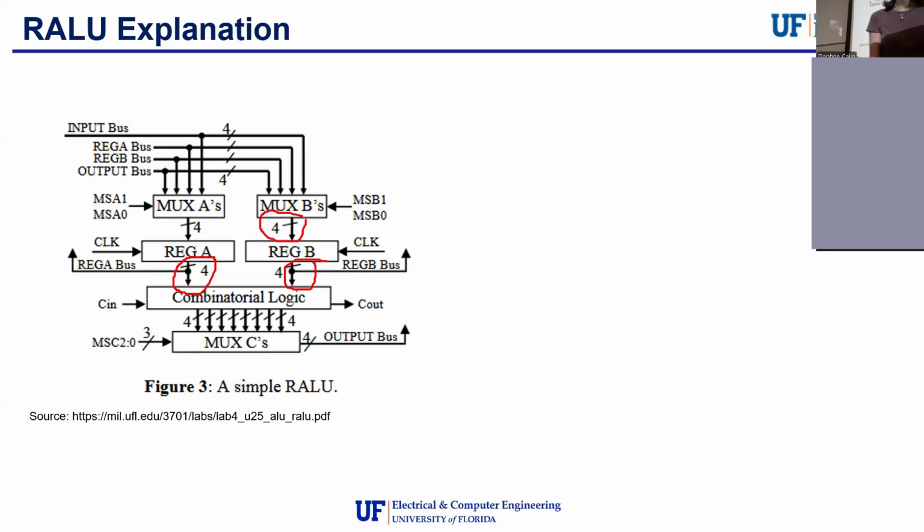Okay. For the presets and pre-clears on the flip-flops, do we have to worry about resetting them at some point? I'm assuming they're talking about the flip-flops to go from register A to register A plus. Okay. So the preset and pre-clear for them? Yeah. What do you mean by worrying about resetting them? You'll probably set them to 0 at the beginning of the lab, or at the beginning of your simulation.